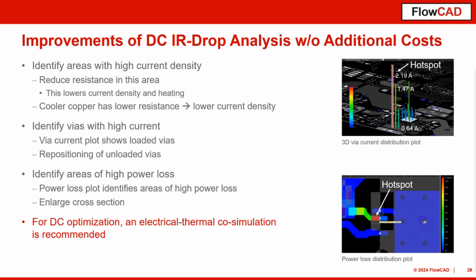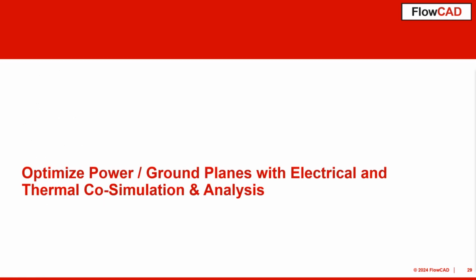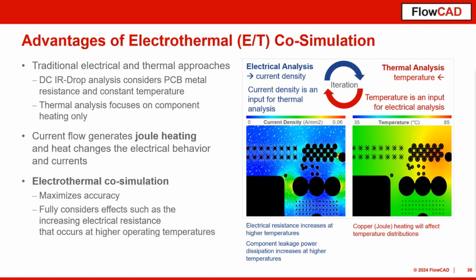So in this case, here is my next item I want to talk about, because the IR drop analysis only uses the electrical aspect, but we also want to go ahead with the thermal aspects, and therefore we need to change over to the Celsius Power DC or Celsius Thermal Solver tools. And what's behind the thermal co-simulation?